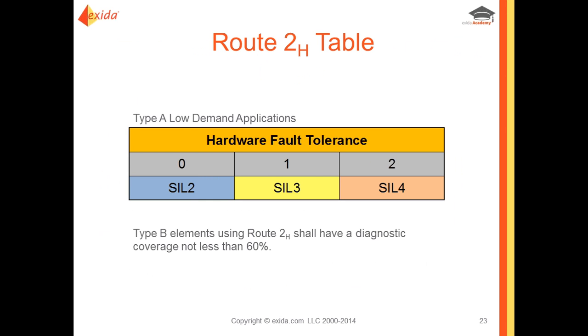So, for example, for a valve in a close-to-trip application, there are no safe failures. That is to say, there are no failures that will cause the valve to close on its own. So even if the safe failures of the actuator and the solenoid are included in the safe failure fraction calculation, the typical safe failure fraction for a final element is considerably less than 60%, which is only good for SIL 1.